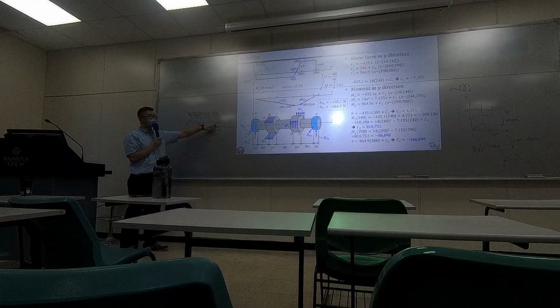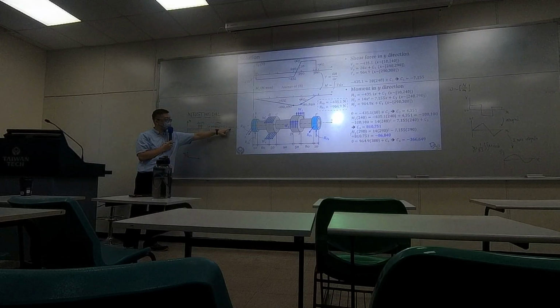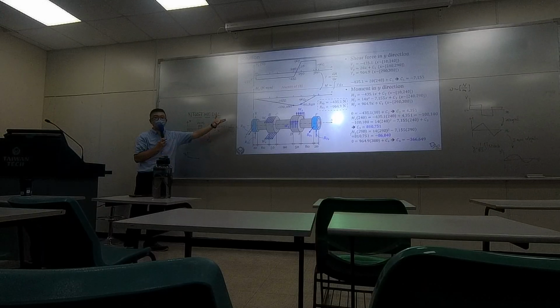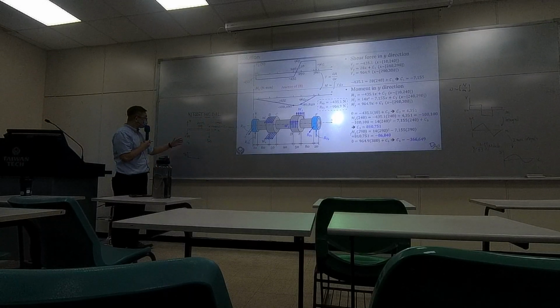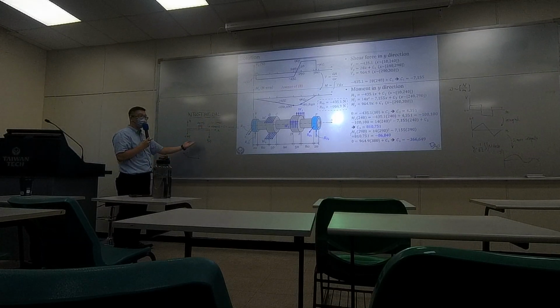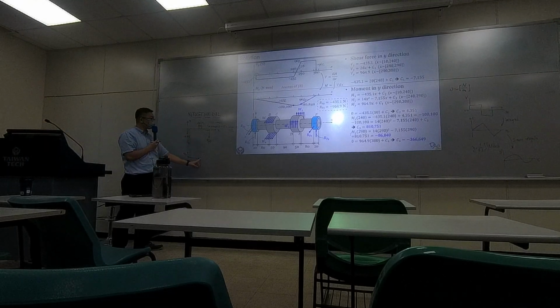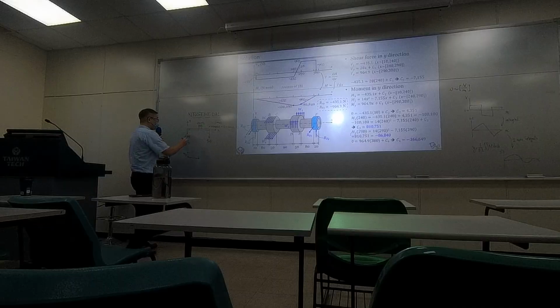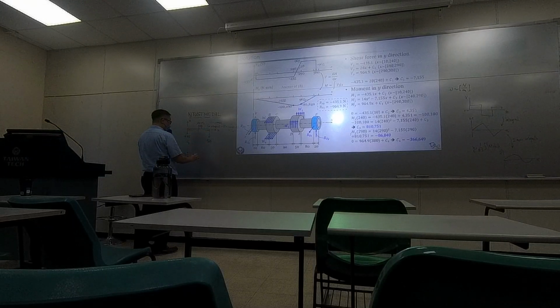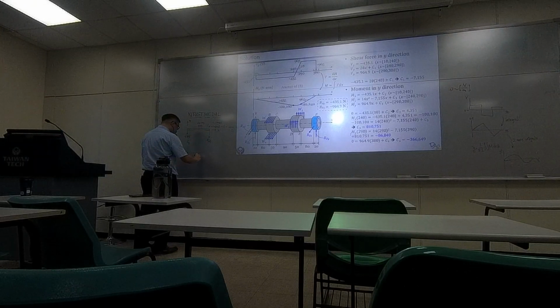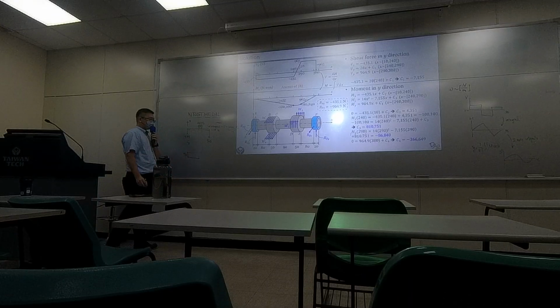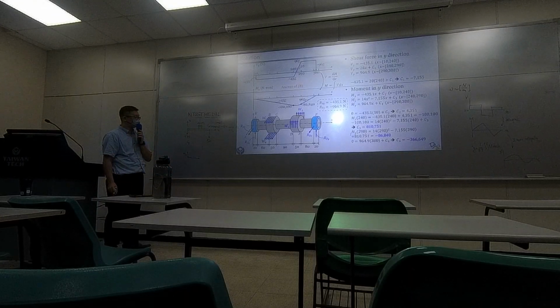So no matter what value you have, that's going to be the slope, and you just need to figure out what C1 is. And usually the shear force is continuous, so you can plug in the value right here to determine C1. So at the end, it's going up like this. Okay? It's a linear function.